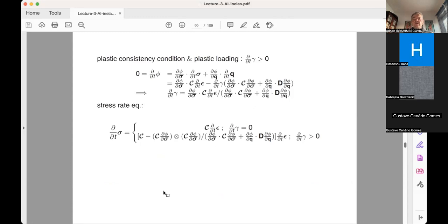and you assume that at t plus dt, that is the next step, you should still be plastic, in which case phi dot should be equal to 0. That allows you to compute your plastic multiplier that would allow you to keep plastic admissibility of the stress. And then finally, you can have an elastoplastic modulus.